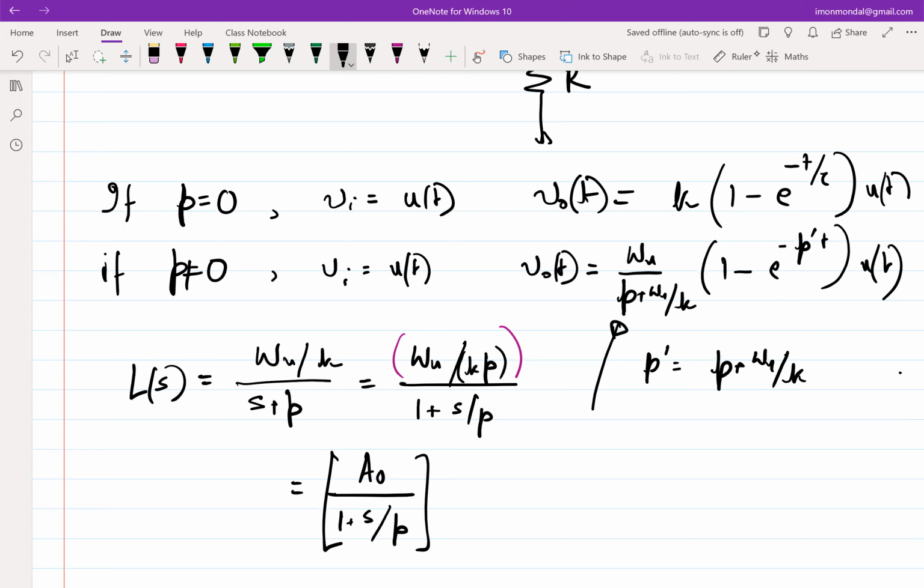So you have moved by a factor of 2 on the x-axis. By what factor should you come down? In dB? In real? 2, right? That's what log scale, log plot means. Whatever factor you go on the right, you go the same factor on the y-axis. So this will be A0 over 2. Right, from there you can go ahead and figure it out.